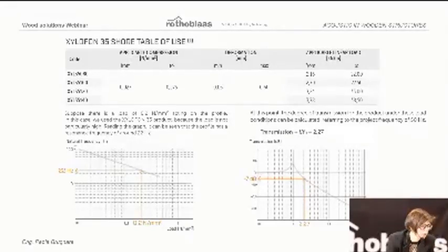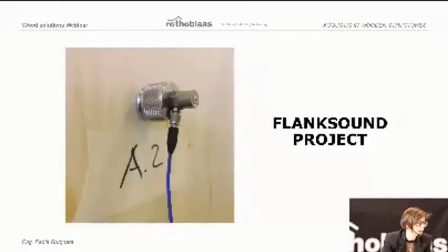The table of use is defined considering that the profile should work between 20 and 30 Hertz. So in this case, the applicable compression is already pre-calculated by us in order to have the minimum and the maximum value, in order to guarantee that the profile will work in the range between 20 and 30 Hertz. This calculation that we have seen takes into consideration the profile working, but it does not take into consideration the influence of the fastening system.